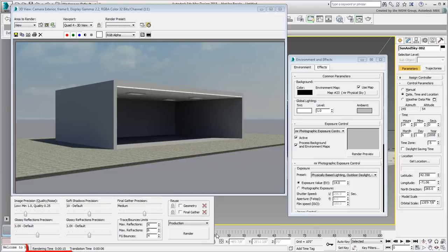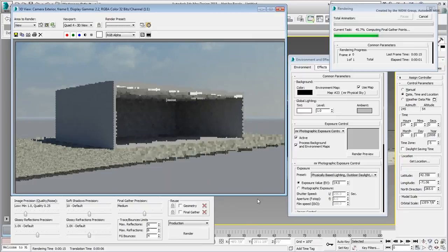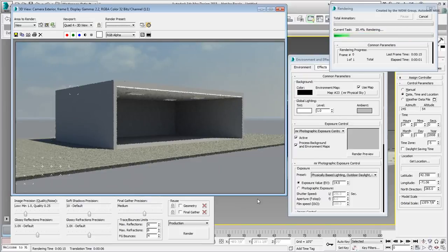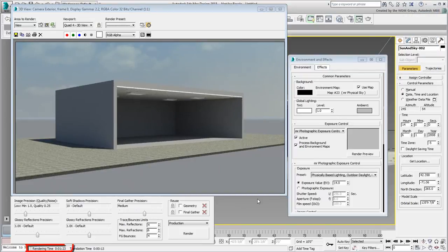The same scene that took 15 seconds to render a moment ago is now taking about 1 minute 20 seconds, and this is a very simple scene. Personally, I always try to look for ways to keep rendering time at a minimum, even if I have to rely on non-physically accurate methods. One of my favorite methods is to use a light source for ambient lighting only.